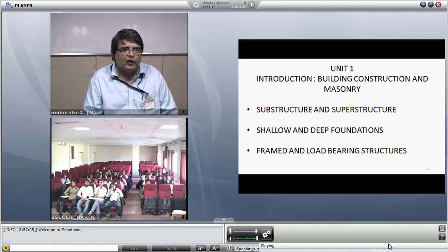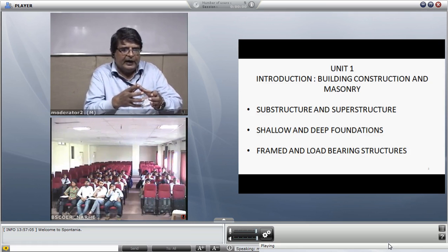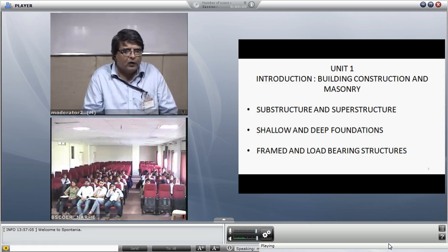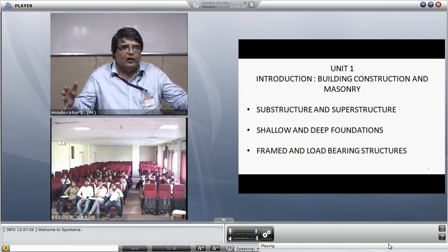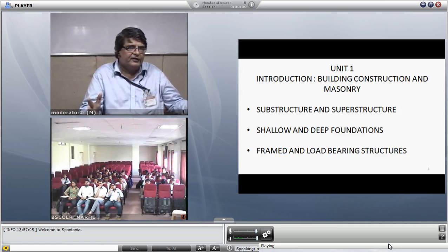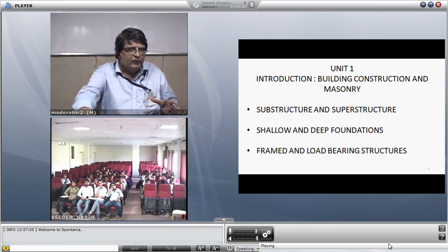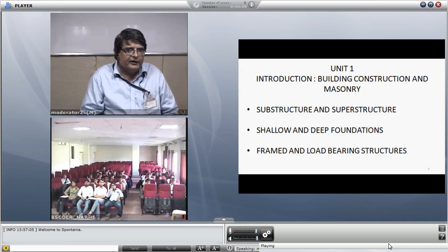Same thing happens with columns. When columns are as they are, if they are put on the ground, the force coming on them will be transmitted over a very small area, and the columns can pierce easily the ground. But if you increase the base of the column and provide a pedestal for it, then the same force coming over the column is spread on a larger area.